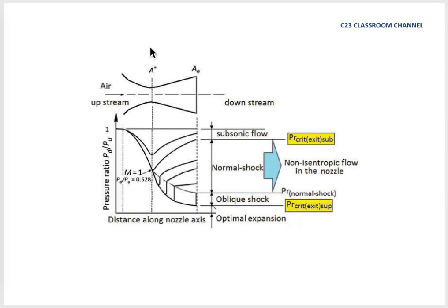So this is another chart to show the same idea, which is that at the throat here, the Mach number should equal 1. And then it goes to the diverging section here, and then it depends. Sometimes it could reduce to subsonic flow, which means we might have a design fault, as a lot of parameters will influence this. Or we could have supersonic flow here, and we have a shock wave to reduce it back.